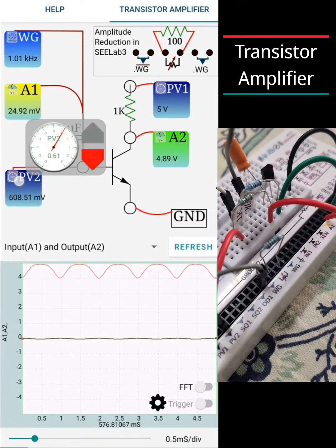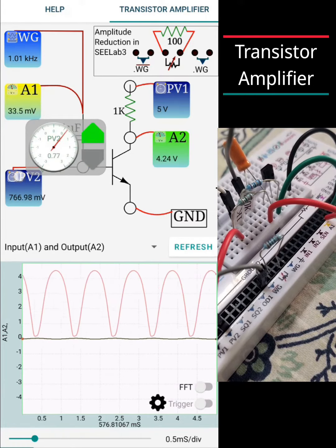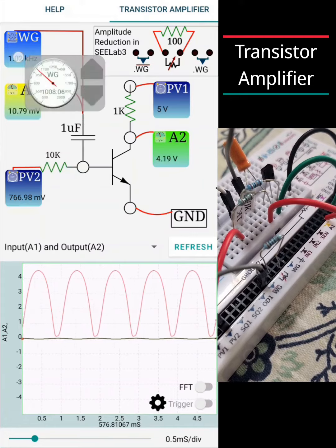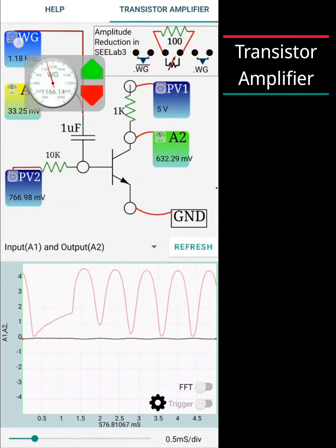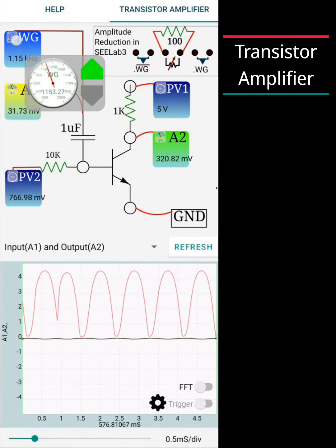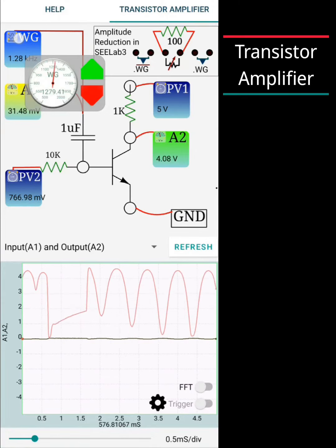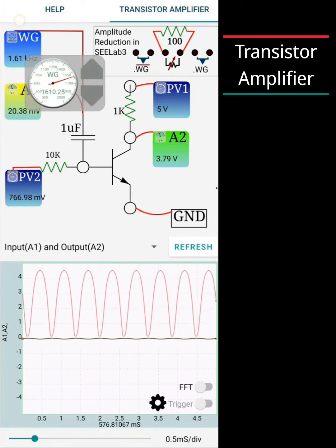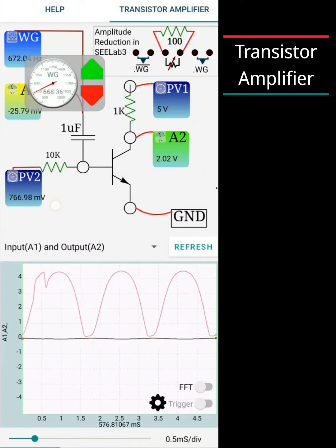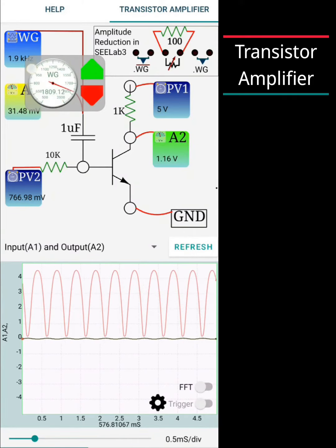And the actual signal comes from WG, which is a sine wave generator. And we're dividing the amplitude of the sine wave, we're making it very small, to the order of around 4 millivolts, using a 100 ohm resistor across the divider pins you find on the C-Lab device.